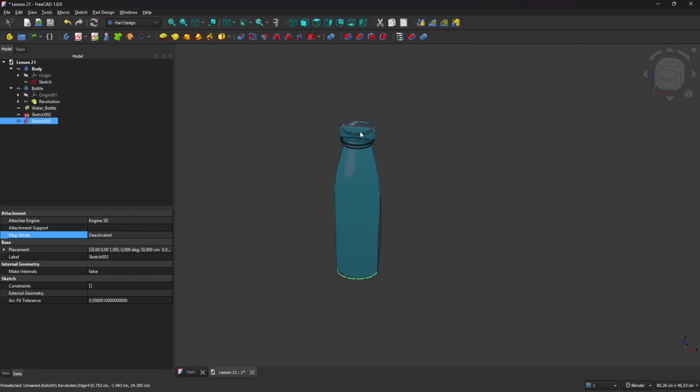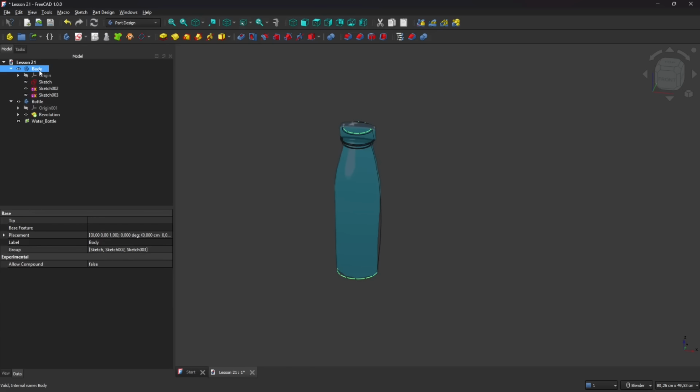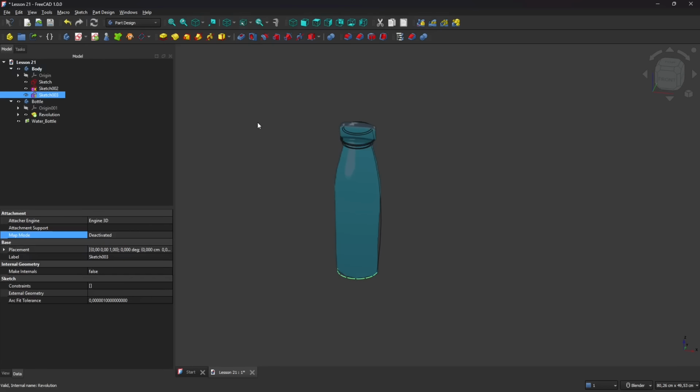And as you can see here, I have another one on the top. So select the bottom one and loft, and cannot use the selected object. Selected object must belong to the active body. Okay, so we need to put this into an active body. So I'm just gonna slide them in here, which is the body I created at the beginning. And now let's do it again.